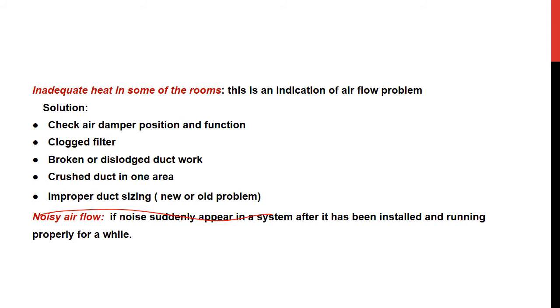Noisy airflow can be an issue. Something could be rattling in the duct, a part is loose, and duct is subjected to a flow of air, and air can cause a lot of acoustics. Duct is a very hollow pipe, so any kind of noise will be magnified and cause you to have a very large noise. So it's good to know where the noise is coming from. And again, noise is an issue that some people notice more than others. So if you have a noisy airflow, you might want to go and check the duct. Also check the fan belt, check the vibration, and check the connections or fasteners for that duct.